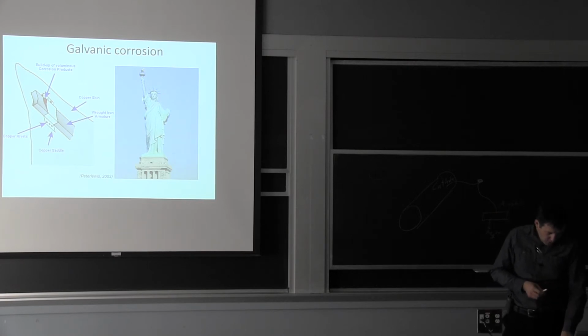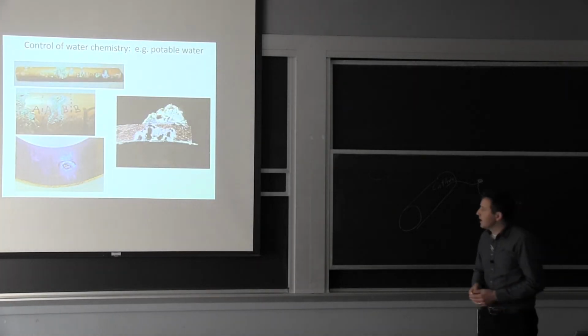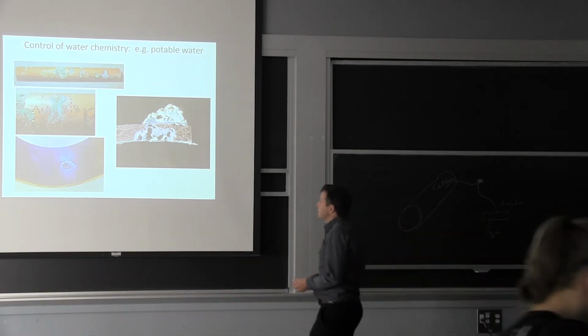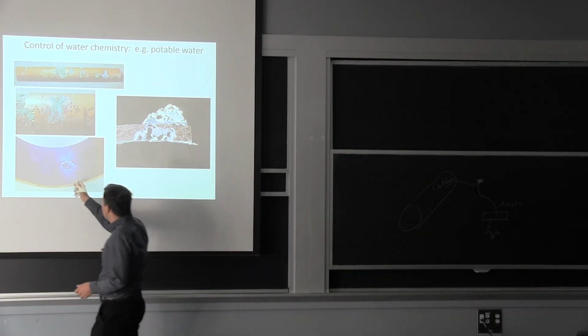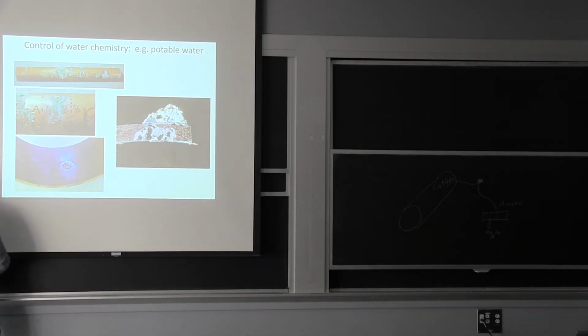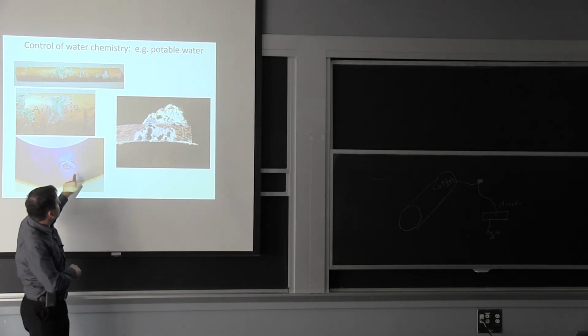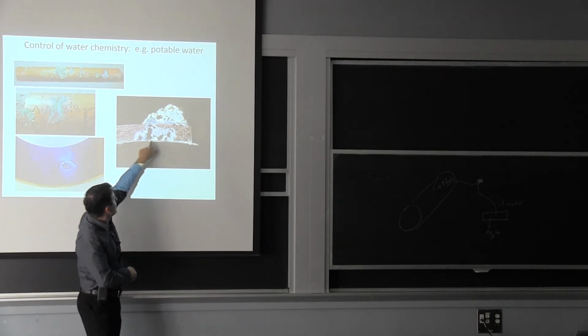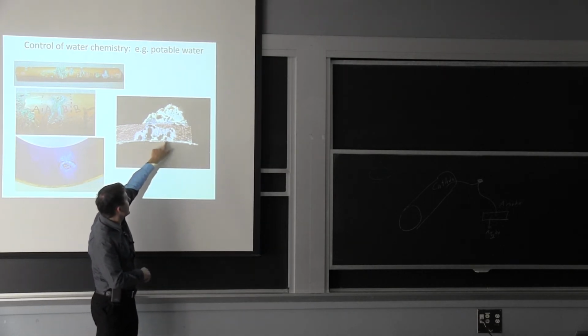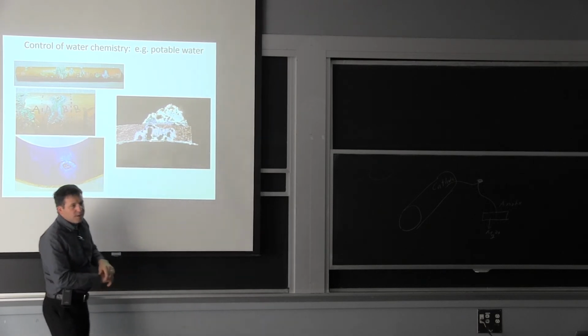Let's go to copper just a little bit, because I think it's good for you guys to be exposed. This is coming off a potable water system, the hot water system in a big building. And you can see the little holes in this image. So the whole pipe looks great. You see the wall thickness. And then the little hole we see is a little bigger on the inside. So that's the inside diameter in a cross section. And then you have a little bit of a hole on the outside.